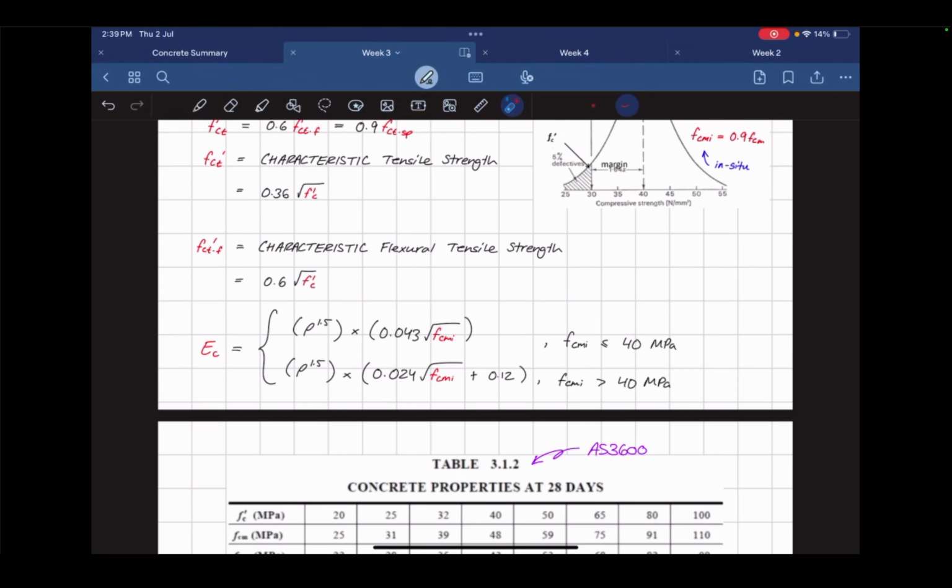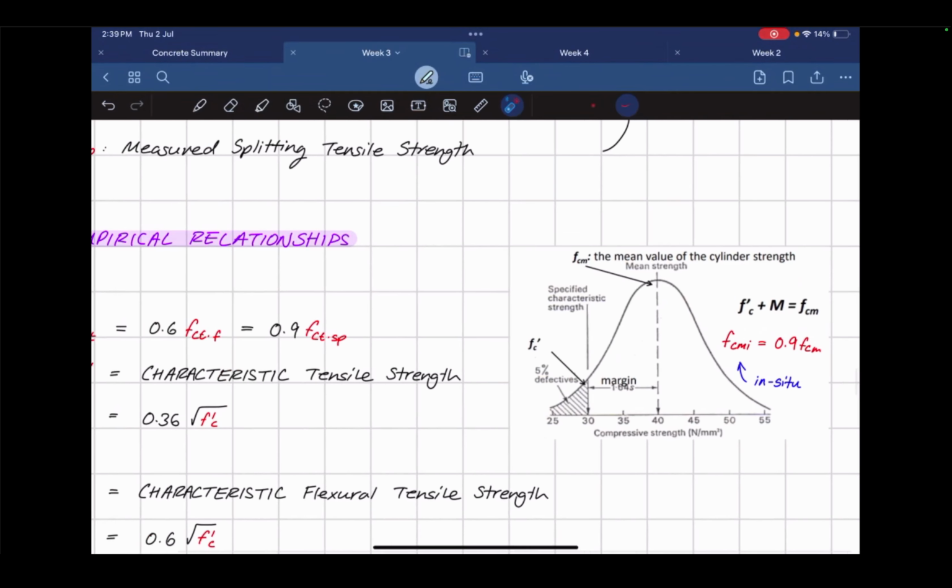What's the part that you can't explain? Why would you use the bottom 5%? Like what I explained, it's the worst case scenario, the worst 5%. It's to do with the safety factor. Of course, we're not going to take the best case, because people could die. But there's an actual reason for the difference between characteristic and mean. Is this in our course? Are you saying why don't we take the bottom 10%, why is it 5% specifically? It's from your lecture slides, but they're not going to test it as a theory question.